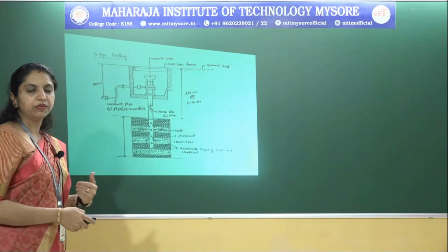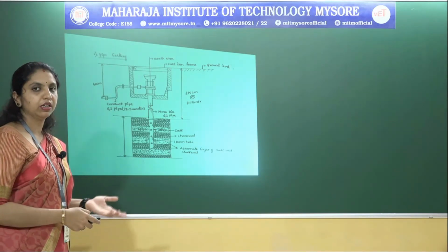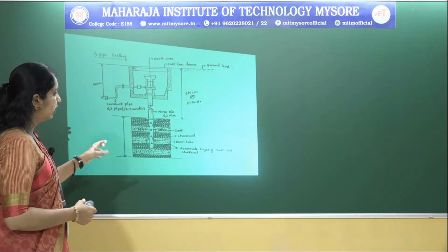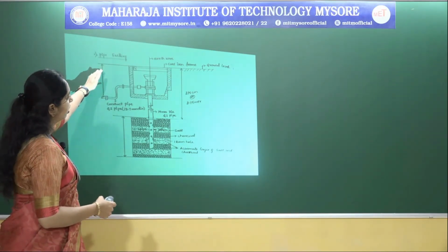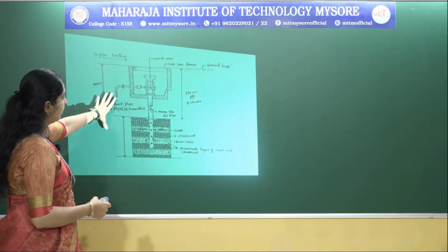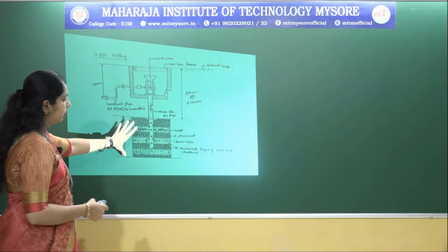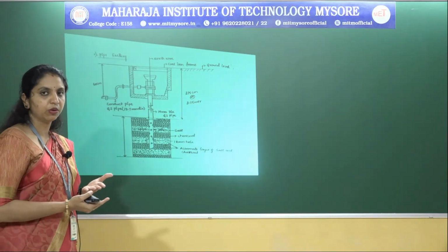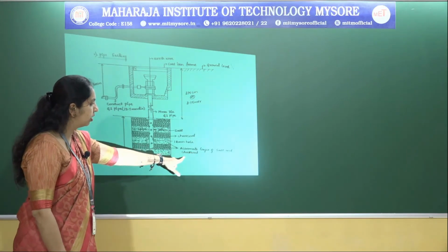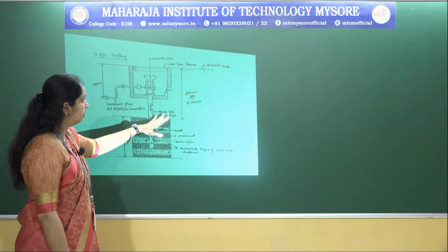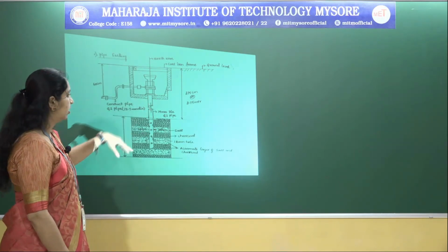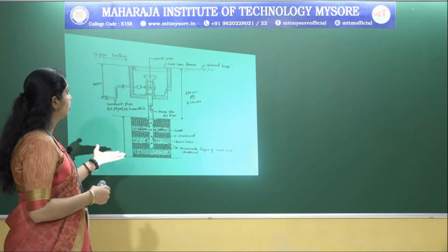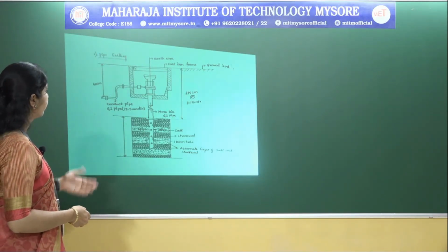And we have different types of earthing. One we call pipe earthing and another one is plate earthing. In pipe earthing, you can see here the ground level. These are the equipments that we keep under the ground level, and of course at the bottom level you can find alternate layers of salt and charcoal. As you can see here, alternate layers of salt and charcoal should be done before we keep all these equipments under the ground. This is the example of pipe earthing.